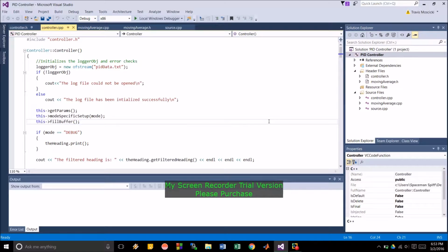And you also want to do things like reset it when you get a new set point. If it gets just over a certain value, just standardly reset it, because again, if left unchecked, it's like a memory leak where it's just going to be filling up, making this I term bigger and bigger and bigger.